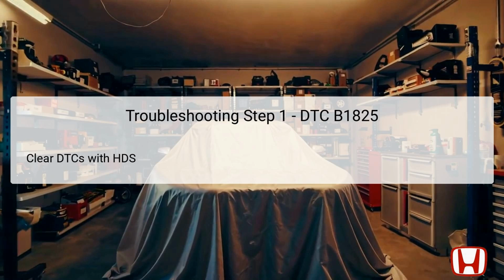To initiate the troubleshooting process for DTC B1825, the first step is to clear any stored diagnostic trouble codes with the Honda Diagnostic System, HDS. The HDS is an essential tool that automotive technicians use to retrieve and clear DTCs effectively. By resetting the system, it allows for a fresh start in monitoring the vehicle's performance.